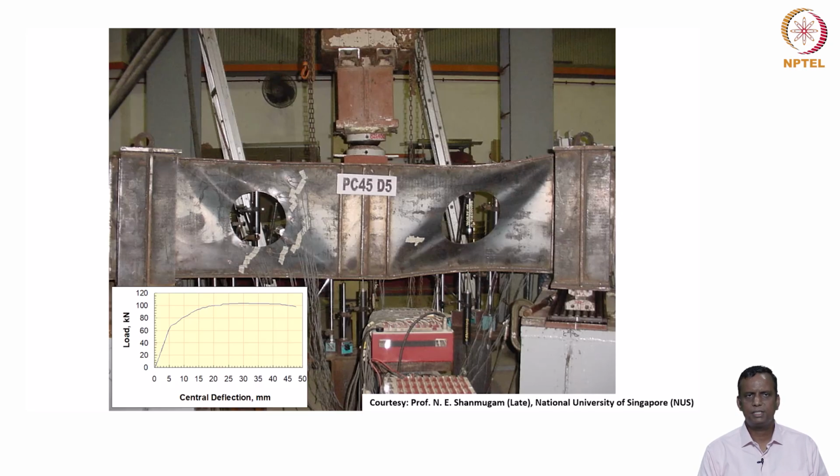The formation of tension band on the left side of the girder is towards us, and the formation of tension band on the right side is away from us, and this basically is a result of imperfections. When the imperfections are towards us, the tension field band also happens in that same way. Basically, buckling is sensitive to initial imperfections, and as a result the buckling formation follows the imperfection trend, which is obvious in this case. The left hand side is towards us and the right hand side is away from us.